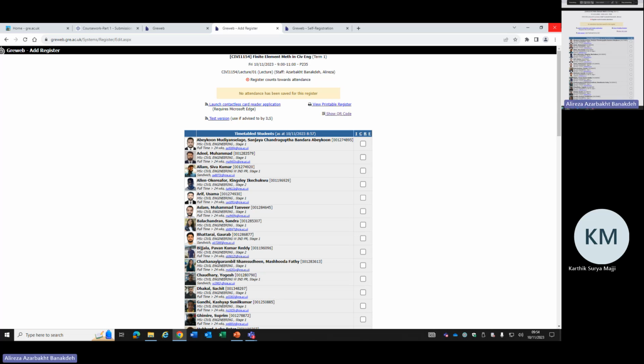But in that case, if you're working with ETABS, when you say a story is this one, you're working in the XZ coordination system, not XY. That's the point. When you simulate this in ETABS and you work in XZ, don't mix it up with this.